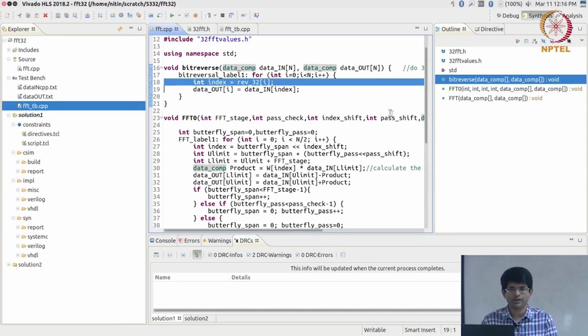From a hardware point of view, strictly speaking, this is terribly inefficient, because bit reversal in hardware is an almost trivial operation. It just involves wiring, there is no hardware at all involved, right. But writing the code in C to do that is not so trivial, right. There is a function called reverse in the APFix library which could potentially be used over here. You can experiment with that and try it out, but if you do not have access to such a function and you try reversing bits in C, you will find that it is actually a very complicated process. And if you write that code, it just becomes a synthesis nightmare, totally not what you want to do at all. So, you use a simpler approach, which is basically you pre-compute the bit reversed values and store them.